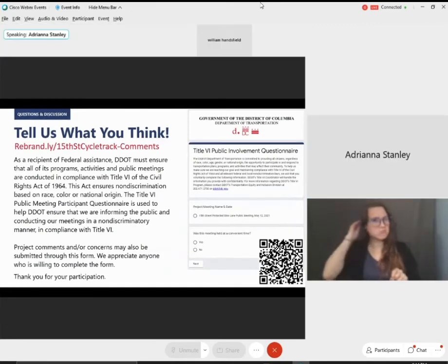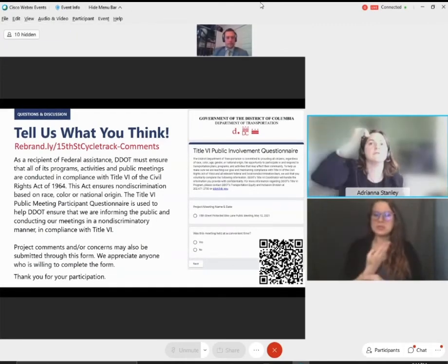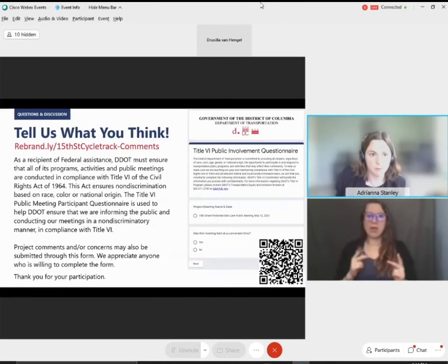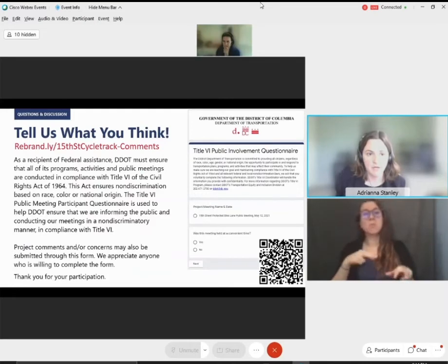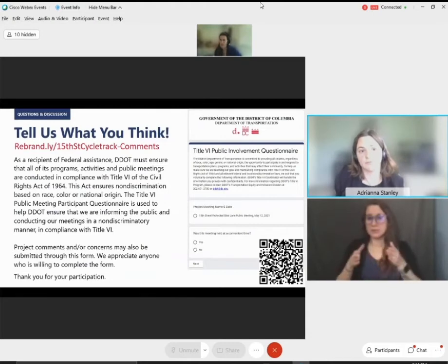Yeah, definitely. So we're using a few things in order to make sure that pedestrians have a little bit more security when they're walking across the street. As I touched on in the presentation, we're providing protected only turning movements across the cycle track. And so we're going to be holding vehicles making those turning movements that would be in conflict there.